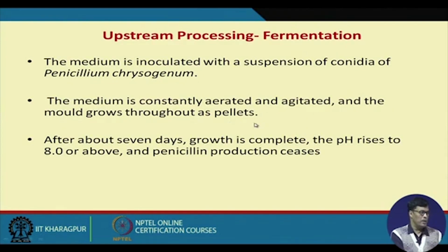Here again let me point out that in the case of a fungal fermentation process, we use the stirred tank reactor. In the stirred tank reactor, we use a mechanical agitator, and it has been observed that if we put the agitator on from hour 0, it will affect the growth of the organism to a great extent.